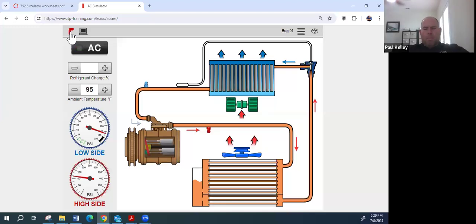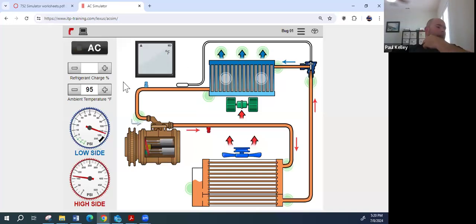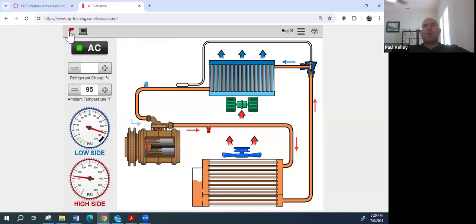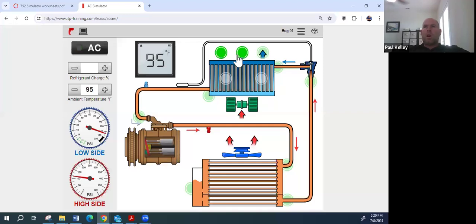Technically, yeah, I'd probably skip the fan part because really it should be able to make pretty good AC without the fan. Now, if you wanted to be really thorough, you could use the fan, but the reason I don't use the fan is if there is an issue with this vehicle's fan and I put a big fan in front of it, I'm basically masking the problem. So I would do everything except for just the fan. So I'm gonna take this thermometer right here. I click the thermometer and I hit the center vent and it's blowing at, what would you call that?